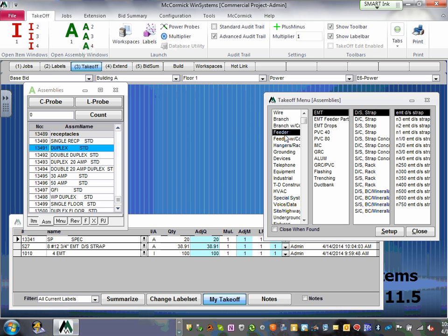As you move through, Derek, look how many circuits you have in that room, because you have to remember you're using either 12-2, 12-3, or 12-4 conductor. So if you have one circuit, try to group them as you move through these conductors. Any comments, guys? Any questions? Derek, is this enough to get you up and running?